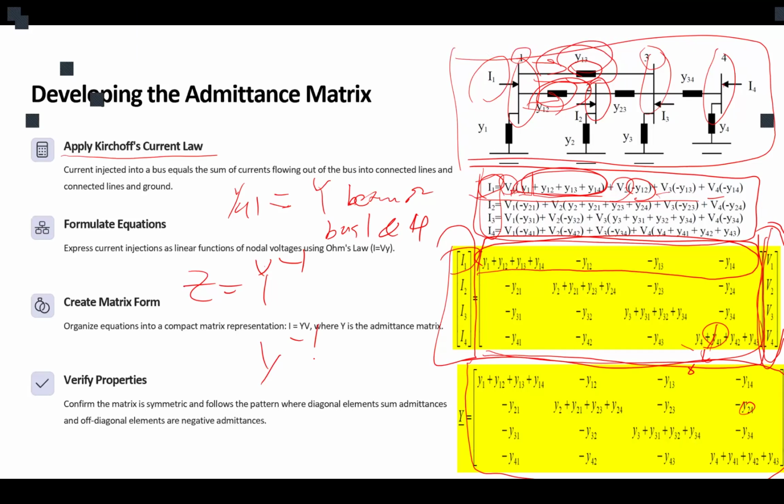So this is the difference. This is the concept I want you to think about. Where do those zeros go? Because we don't have a straight connection between 1 and 4 in the admittance matrix in the topological graph, so it's 0. But for the same system, if I show it by impedance matrix, now there is a quantity that shows the connection between 1 and 4.